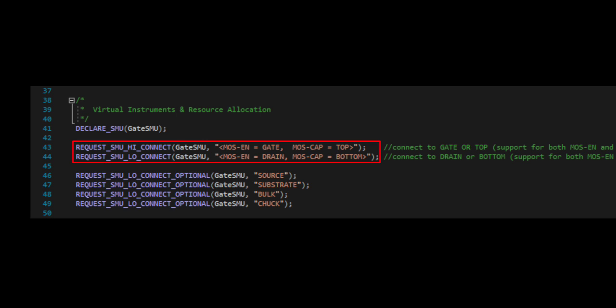Next is the device terminal connection. If you have only one device type, there is simply the string of the terminals of that device type. If you have multiple device types, you need to use the structure you see here to tell the algorithm which device type's pins are used for which connection. Next, the MOSFET device type has additional and optional terminals. The minimum MOSFET has drain, gate, and source, but optionally can have additional terminals defined. We have all of them connected to the drain terminal here.